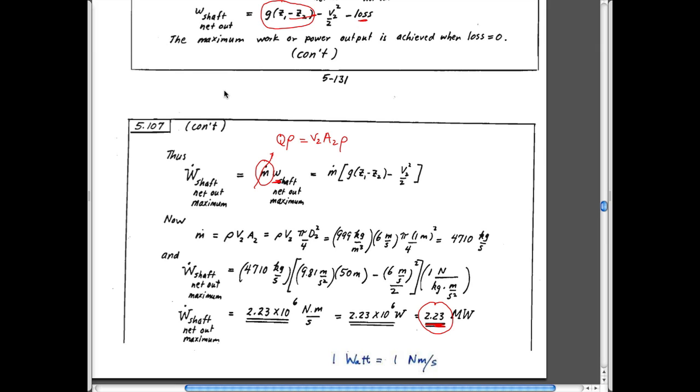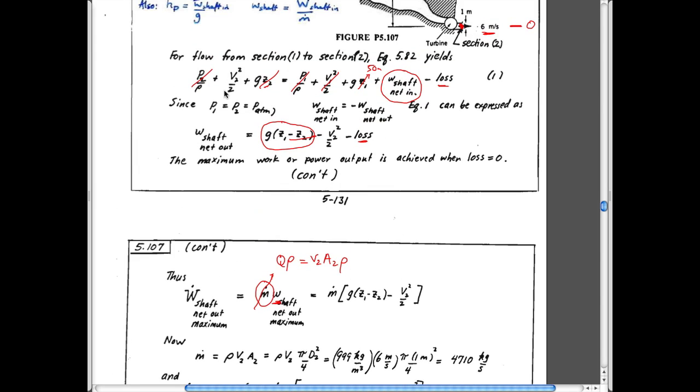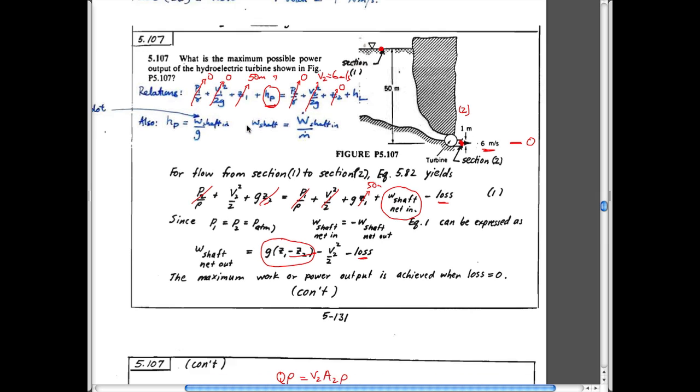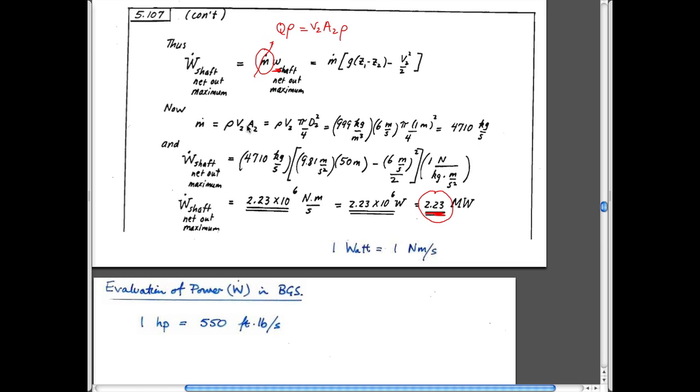And I guess I didn't say it here, but if this is the case, in terms of the sign convention, the magnitude of the watts that you get out of this would be a negative number because you're not putting energy into the system as you are in a pump, you're getting energy out of the system in terms of a turbine. So the magnitude of this term here, as you calculate it, would be negative, which just means that you're getting energy out of the system by our sign convention. So that's worth remembering. Okay?